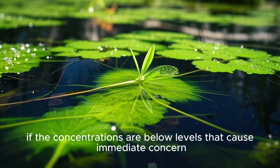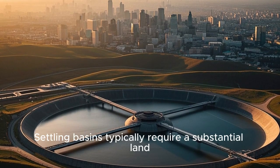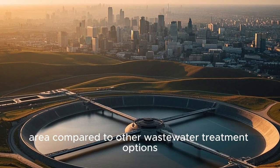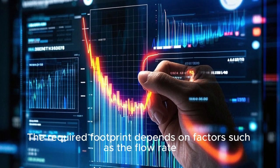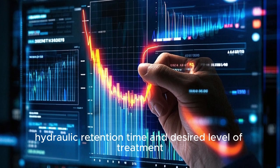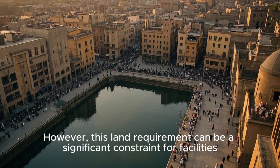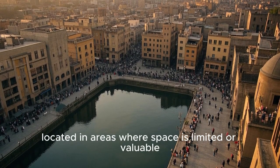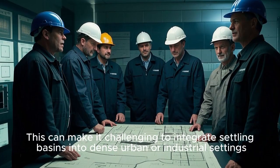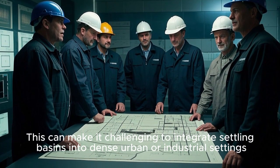A third limitation is the large land area required. Settling basins typically require a substantial land area compared to other wastewater treatment options. The required footprint depends on factors such as the flow rate, hydraulic retention time, and desired level of treatment. However, this land requirement can be a significant constraint for facilities located in areas where space is limited or valuable. This can make it challenging to integrate settling basins into dense urban or industrial settings.